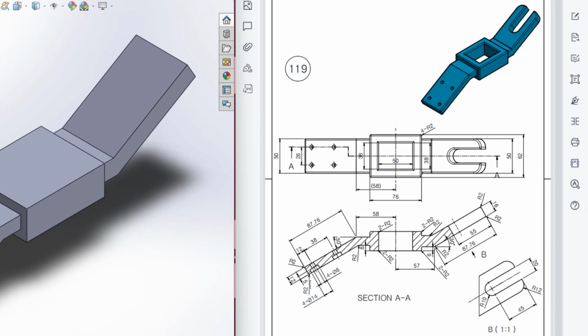Okay, now here you can see we have many extrude cut here, and we have 4 extrude cut in this plane, 4 extrude cut circular hole. So the upper hole are 6 diameter, and the distance from this line to here is 12 unit, and the other circle here is 38 unit apart from the first circle. So if we draw this one and this one circle, then I will draw a center line and mirror other two circle.